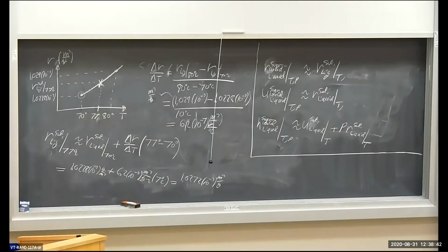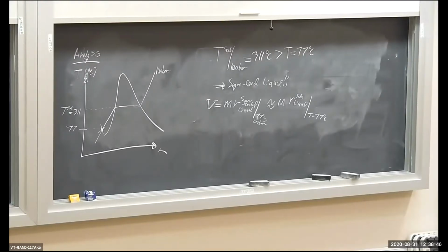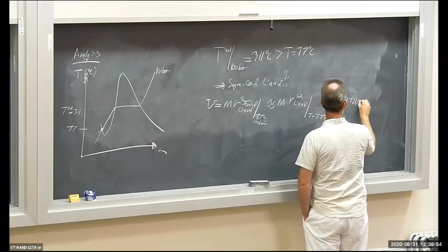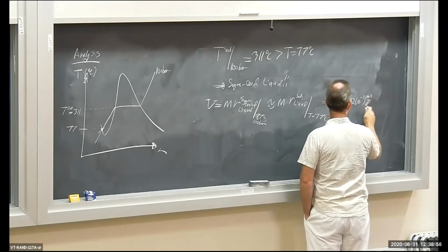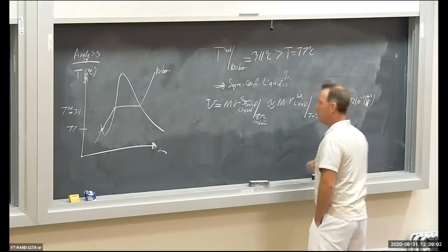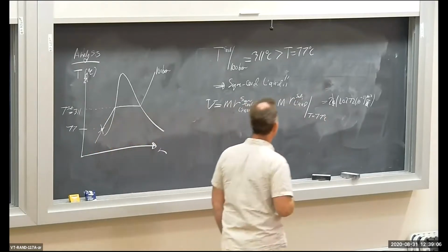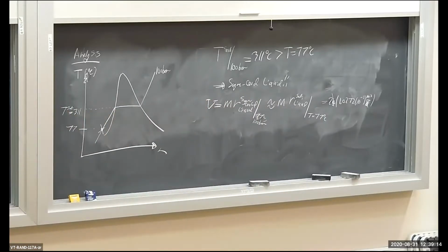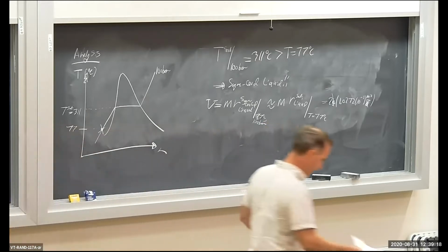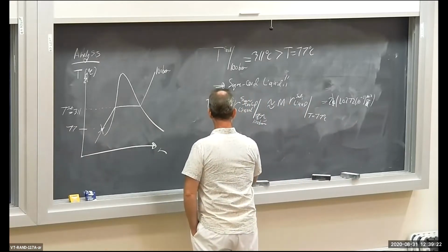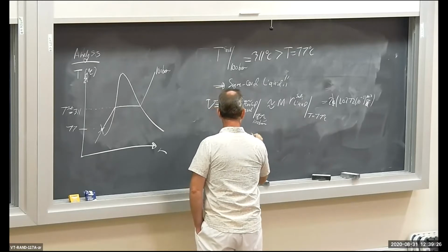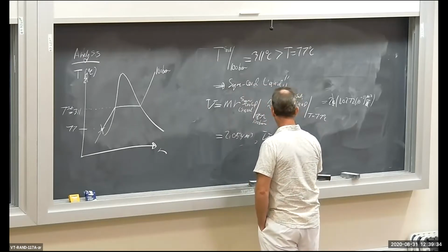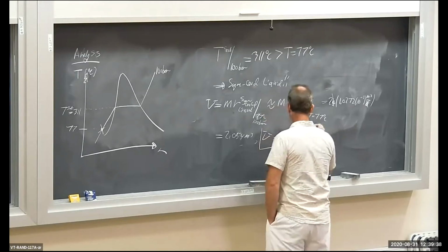1.0272. Let us plug that in and get our volume. The mass was 2 kilograms and 1.0272, 10 to the minus 3 cubic meters per kilogram. The kilograms cancel out and I get cubic meters, which is what I want, and I end up with a final volume of 2.054 cubic meters. So volume of my supercooled liquid at the temperature and pressure is 2.054 cubic meters. So let's put a box around it.